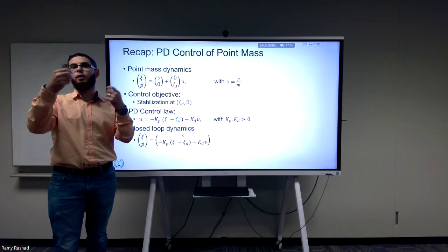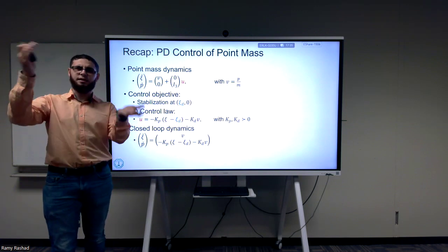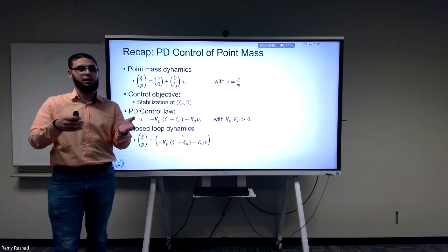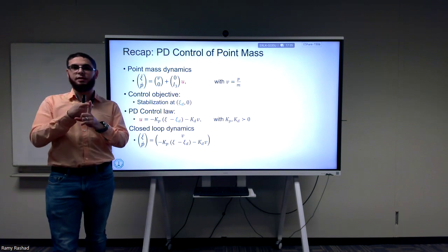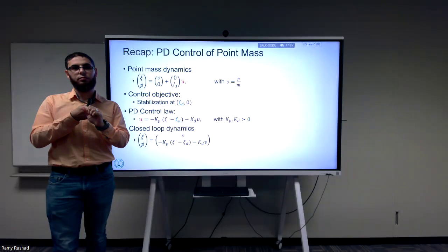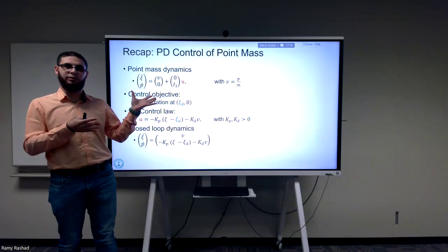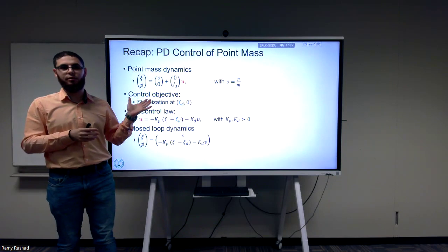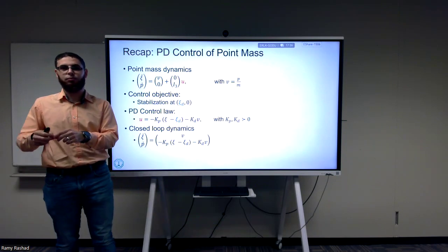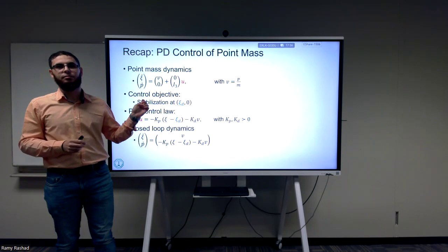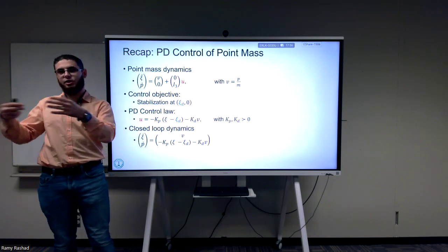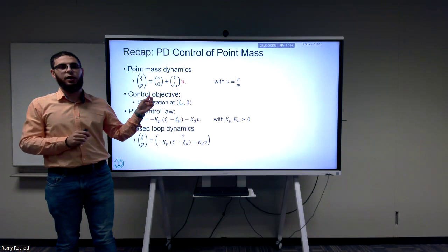Go back to when you were introduced to rising time and settling time and overshoot and all of these nice stuff. They're only valid when you have a linear system that's only second order. So you have to be a linear, single input, single output system. In real life, we don't have these systems anymore. Maybe in small MATLAB code, but not in real life. Maybe, okay, but after a lot of approximations, you can write a system like that. But in real life, we don't have that.